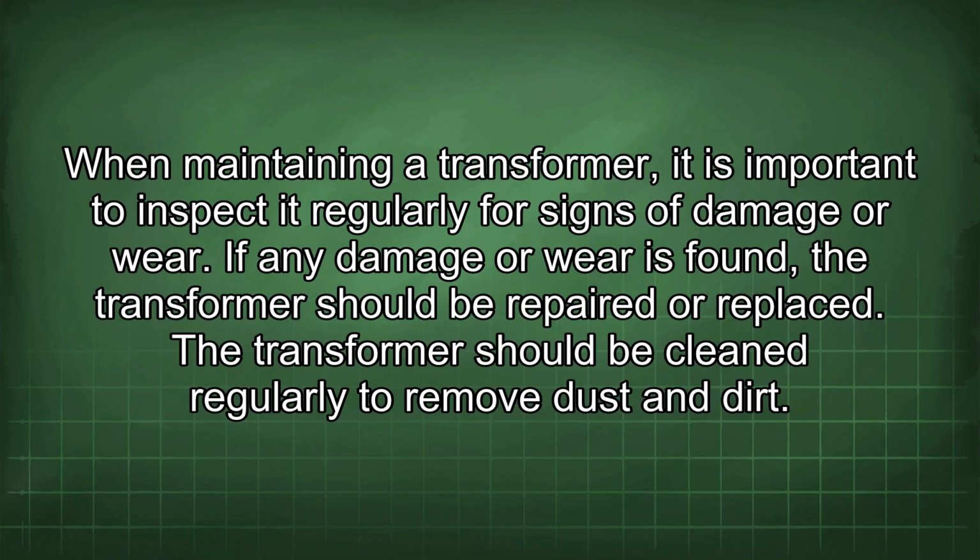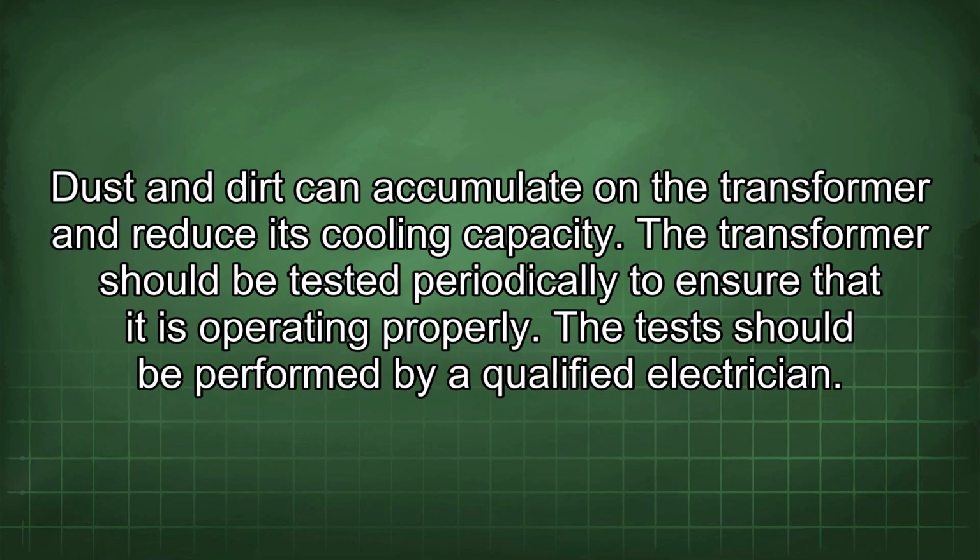When maintaining a transformer, it is important to inspect it regularly for signs of damage or wear. If any damage or wear is found, the transformer should be repaired or replaced. The transformer should be cleaned regularly to remove dust and dirt. Dust and dirt can accumulate on the transformer and reduce its cooling capacity.